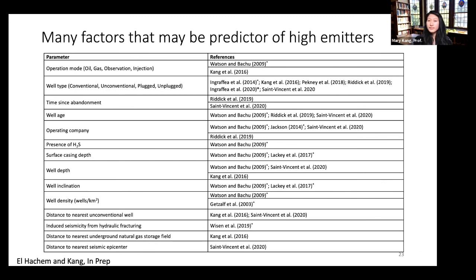That's right. Do you also consider the formations that may be active for that abandoned well, using the neighboring active wells, to know the formations that may be producing this gas behind the casing, or that may leak into the wells because of the loss of integrity of the wells? Do you consider comparing the active wells with abandoned wells and the neighboring wells?